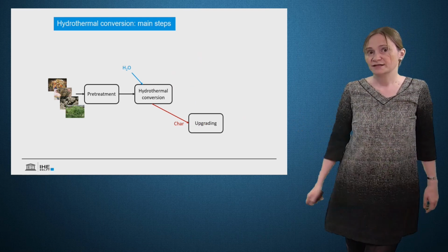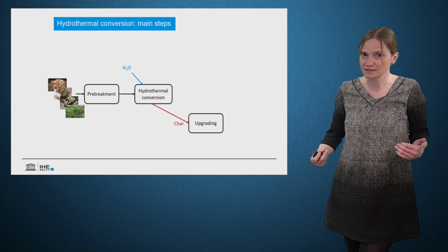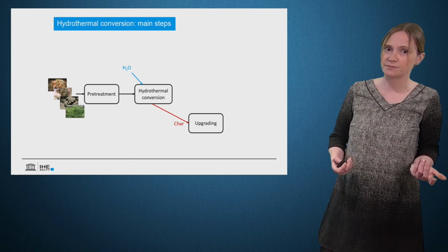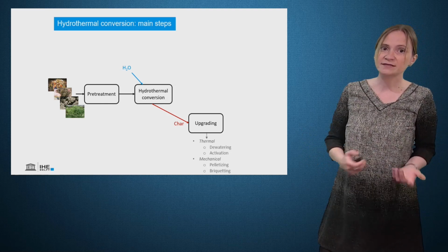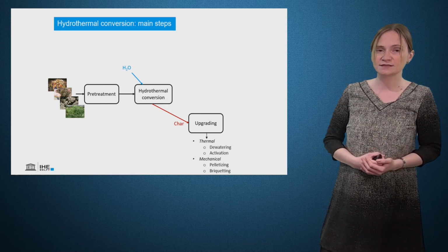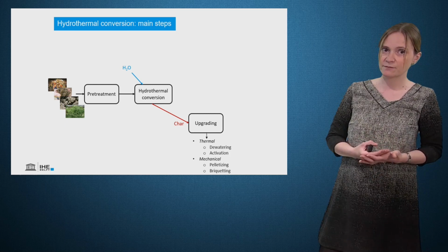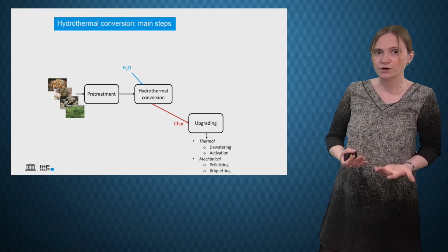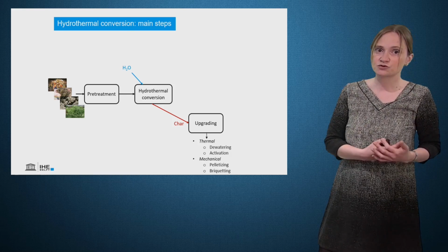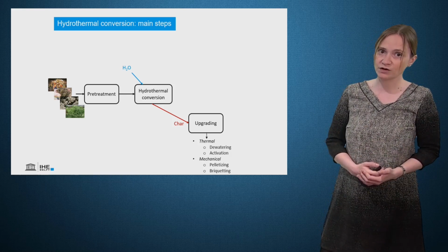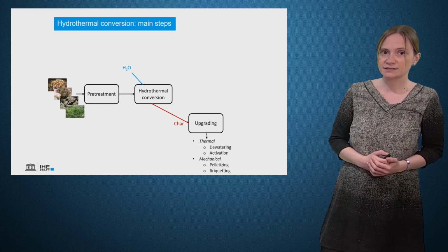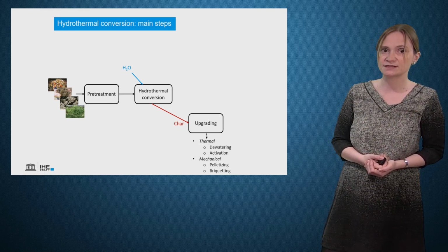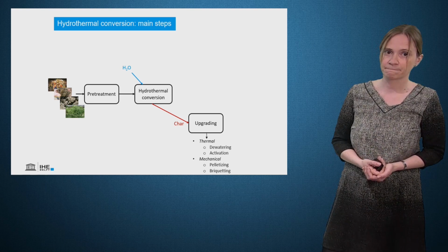What's happening to the solid afterwards? As for pyrolysis, char is often upgraded to improve its properties relatively to the applications. The main difference with pyrolysis is that in the case of hydrothermal carbonization, the char initially contains a lot of water and then needs to undergo first a step of dewatering. Note that this step is much less expensive than drying because the char produced is naturally hydrophobic.